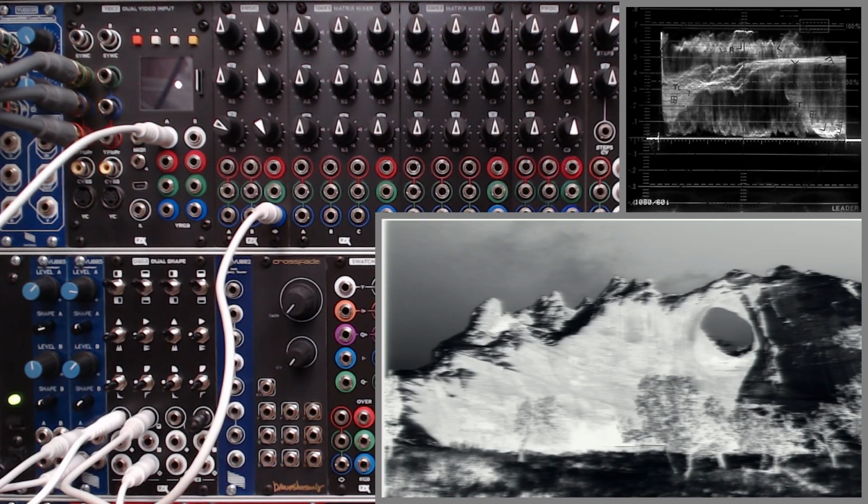If we think that through, then the obvious solution will be to run the signal through a rectifier. What that's going to do is when our video image reaches a value of 0.5 volts, then any value above that is going to get folded downward. And we will get that symmetrical triangle wave that we saw before, except that triangle wave is going to be applied to the video image rather than just a simple waveform.